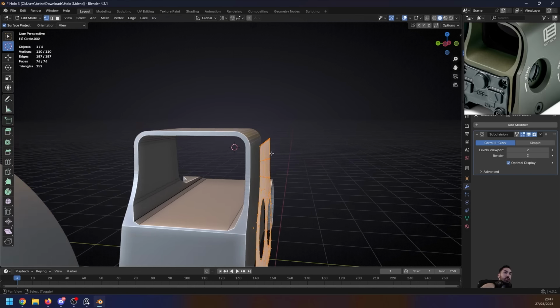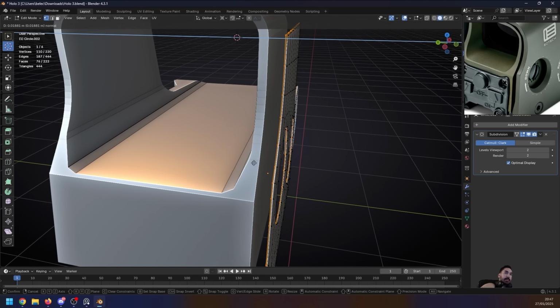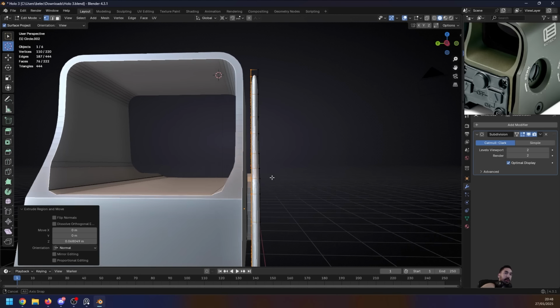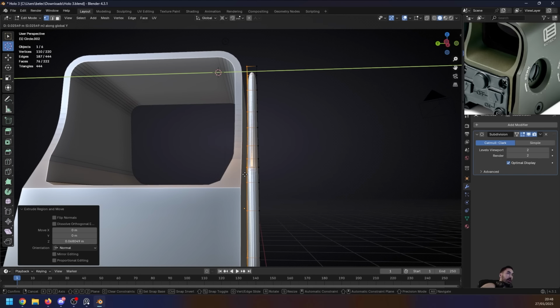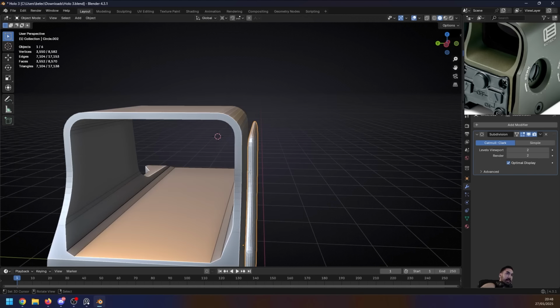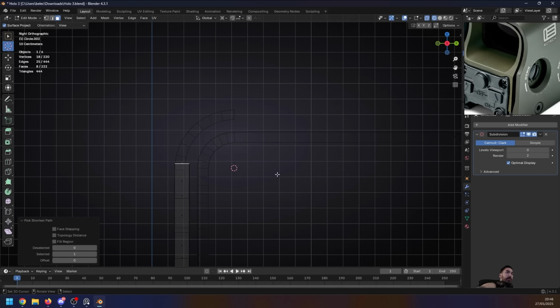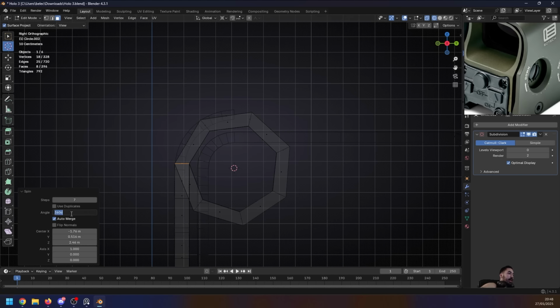Now before we use our spin tool, we're first going to extrude this a little bit to give it a little bit of thickness like this. This outer surface is supposed to be thicker than the gap, so just make sure to push it in far enough. It's supposed to be approximately like this, and now we can just select these faces at the top. We're going to go to front view or something. We're going to press Alt E spin, set the angle here to 90 degrees, and we probably want 8 steps or something like that.